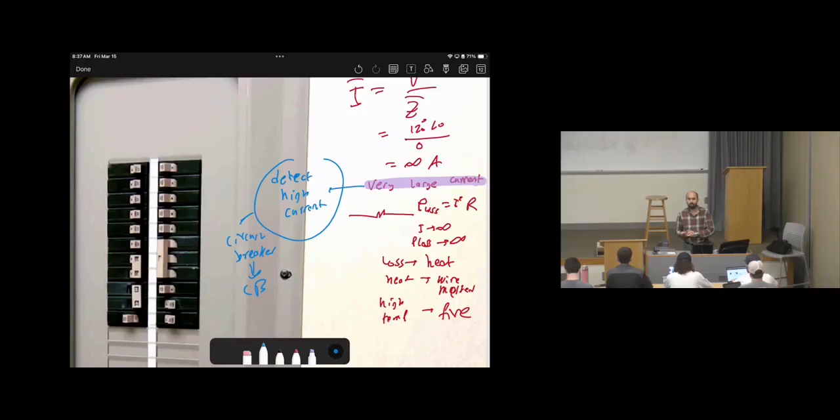There is also something that we call circuit breaker coordination. If a problem happens, something goes wrong, we don't want the main circuit breaker to trip first. We want the circuit breaker associated with this room to trip first. If not, the other one will work. We call it protection coordination.